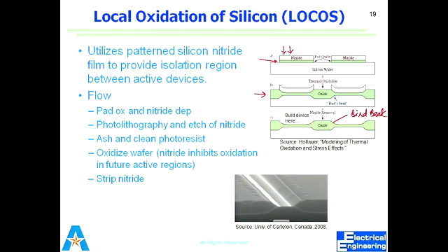Now I want to grow 500 nanometer of oxide in my field oxide, in that pad oxide layer. When 500 nanometer is grown here, it means there would be this beak as well. Bird's beak would be there. Bird's beak encroaches inside, so that bird's beak, the lateral growth, would also be 500 nanometer. 500 nanometer in this way, 500 nanometer in this way.